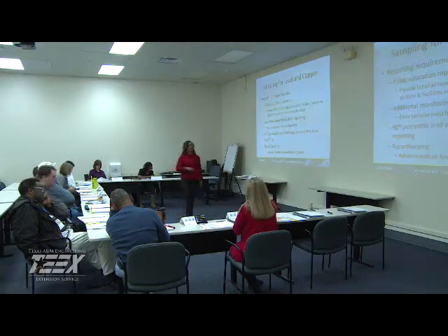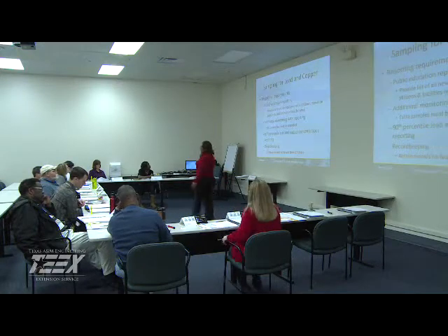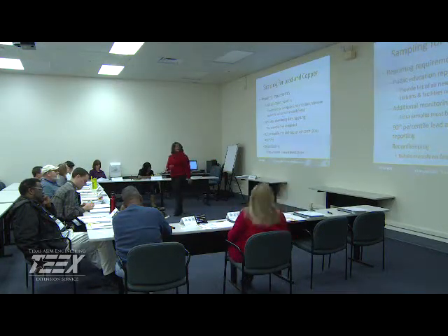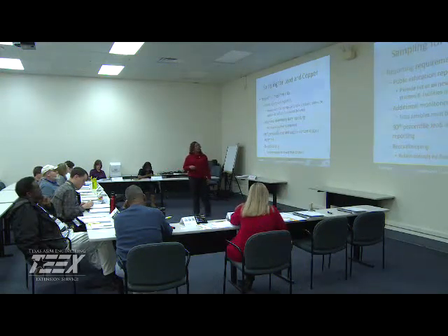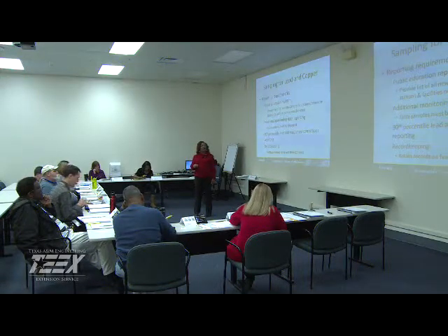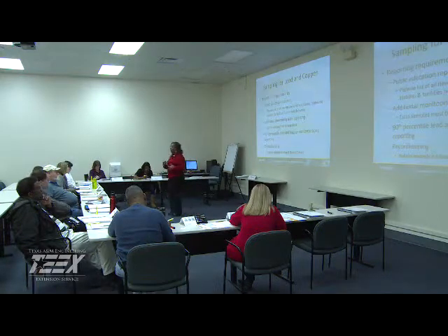All right, what are we going to do as far as educating the public? Again, there's an exceedance of the lead or copper. There's an issue in the 90th percentile. Now we need to alert the public. We're going to provide a list of newspapers, radio stations, television, and facilities. We're going to provide all that to the state where we're doing the initial education.